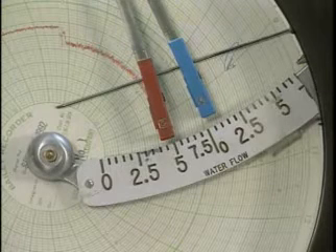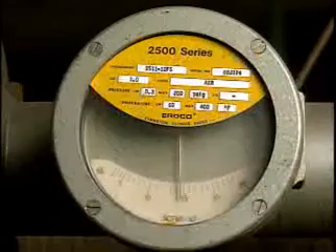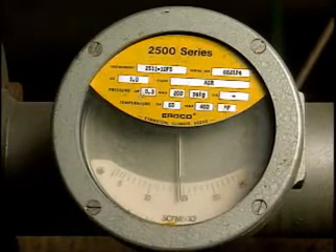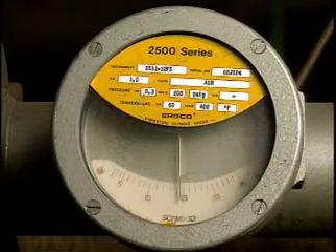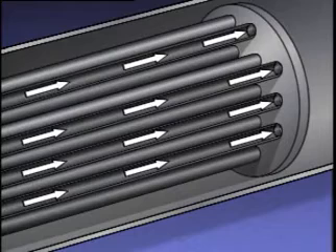The flow rates of the fluids involved also affect the amount of heat that can be transferred. Generally, as the amount of fluid that passes through a heat exchanger increases, the amount of heat that can be transferred also increases. Heat transfer can also be affected by the presence of contaminants in the fluids.